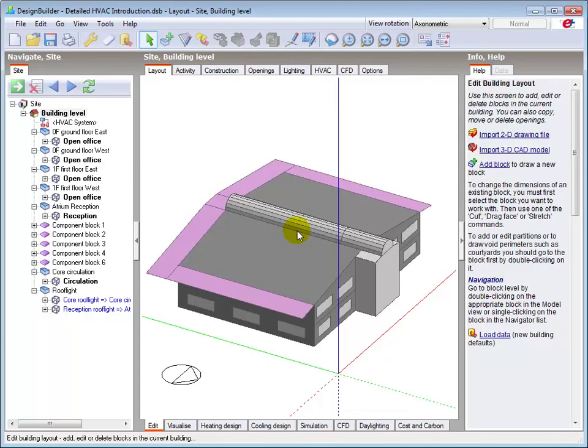You can easily create your own HVAC systems in DesignBuilder by creating zone groups, then manually selecting and connecting HVAC components and editing the model data as required. Before we look at that, I'll show you an even simpler way of creating systems using Detailed HVAC templates. These can be used to load predefined HVAC system types, complete with all components connected. Some of these templates have systems containing compliant ASHRAE 90.1 Appendix G settings, enabling you to very quickly and easily model systems that meet code requirements with a few mouse clicks.